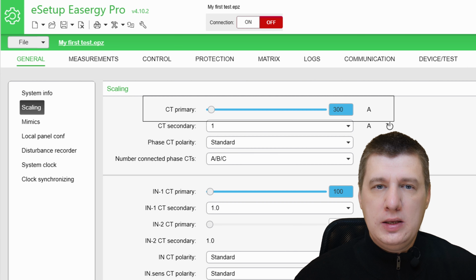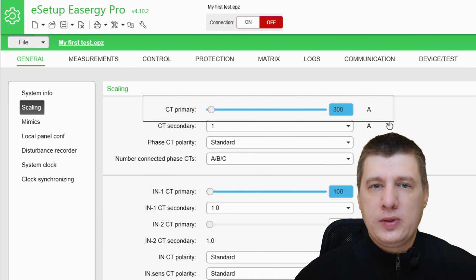For the relay to maintain accuracy during the fault, the CT must be sized so it doesn't saturate. If you're using definite time protection, the CT saturation current must be greater than 1.5 times the set point to ensure the relay receives a clear signal to trip.